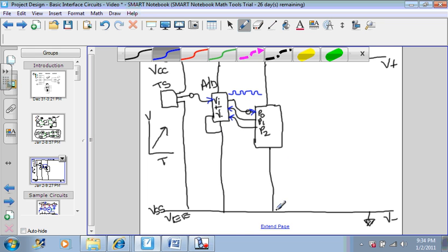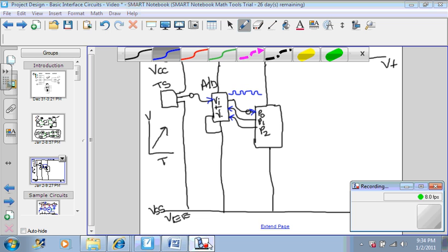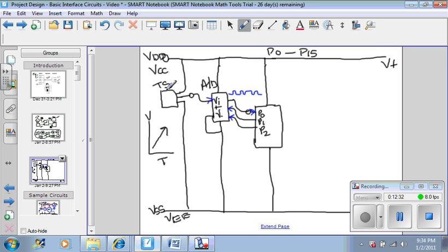All right, that's the end of part 2. I have concluded by showing you how to build up your circuits by taking the component and deciding which part of the component connects to the power and which part connects to the negative and what part of the component is the signal. You get this information from the data sheet.